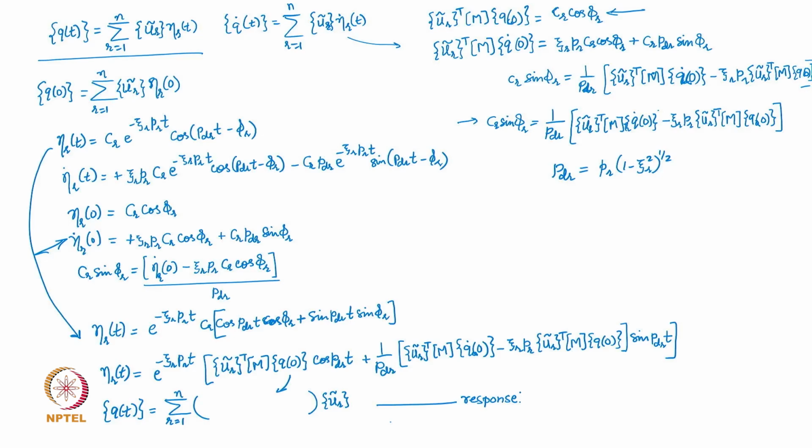These all ultimately turn out to be simple elements or vectors of a size depending on your degrees of freedom. So you prescribe the initial displacement and velocities, and many times it so happens that you give only initial displacement or only initial velocity, so one of those terms is going to be 0.